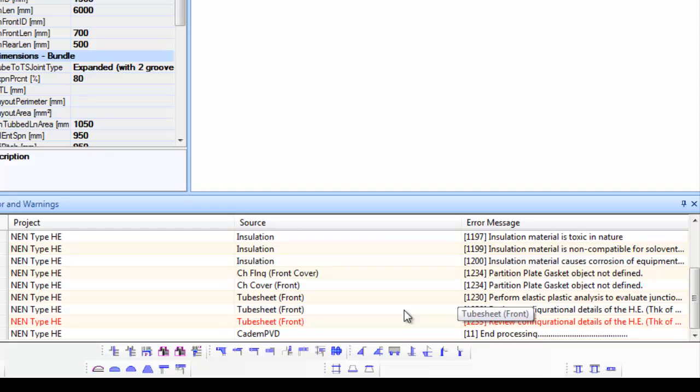The warning number 1230 indicates there are excessive stresses in the channel exceeding the allowable stress. To bring these stresses below the allowable limit, the increase in required tube sheet thickness is very high. Therefore, under such a situation, review of the heat exchanger configuration is essential.